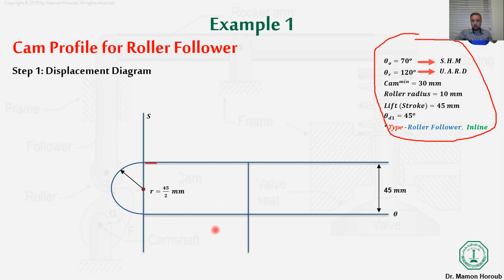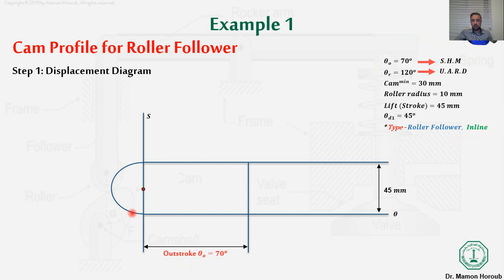So this much amount will be represented by 70 millimeter, which will be equal 70 degree. As I said, every 1 degree will be represented by 1 millimeter. So our scale will be 1 degree equal 1 millimeter. And this is our first period. And we will draw our first period of the displacement diagram based on simple harmonic motion. How will we do that?